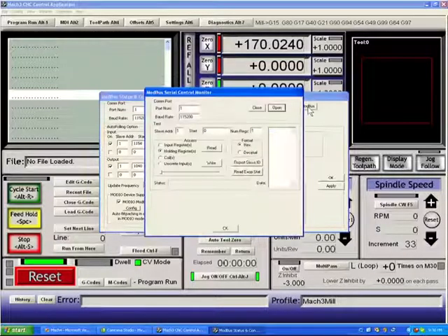By pressing the Test ModBus button, we bring up a special box which is just used to test your ModBus device. You can see here I'm set up for port 1 at 115 kilobaud, slave address 1. If you have several ModBus devices, they may have different slave addresses. This is how you address them on the port to find which one you're going to talk to. At the current time, you could conceivably talk to 4 ModBus devices by changing the slave addresses here to correspond to the various ModBuses.